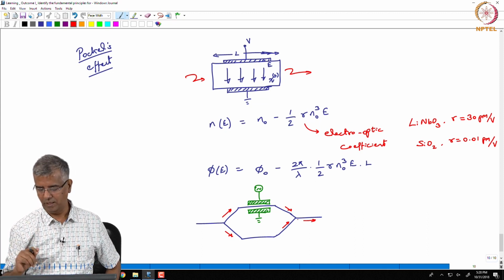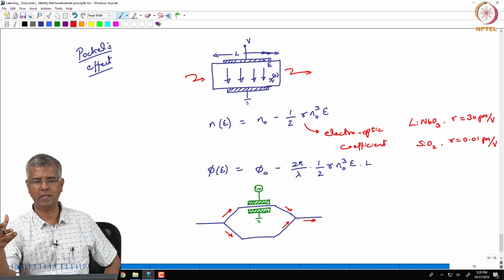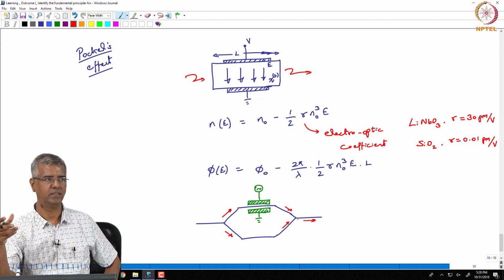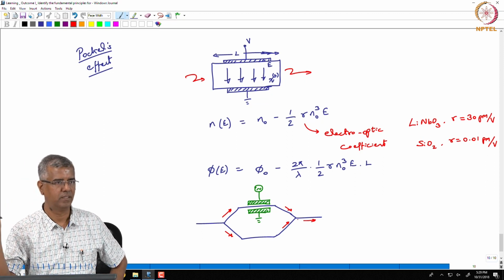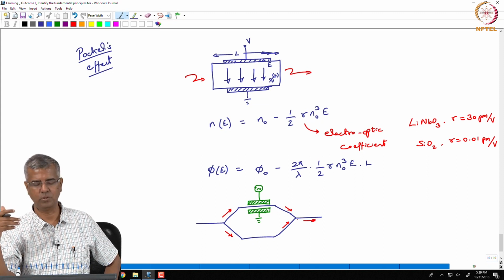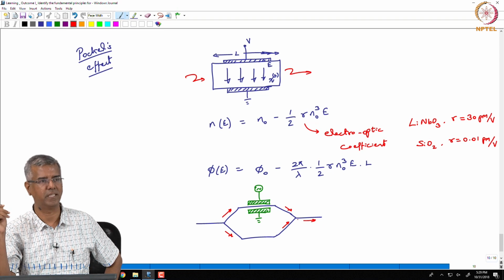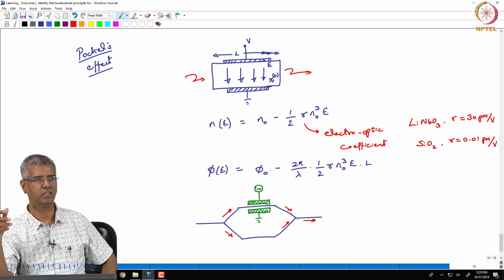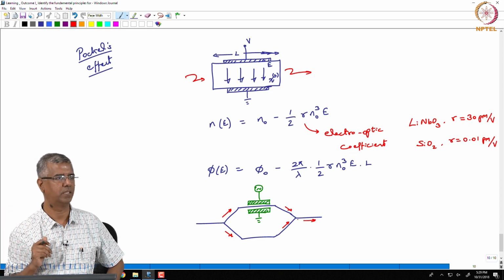So, if I want to communicate data, I have my data, I am speaking now, and let us say this is actually transmitted live somewhere. You are digitizing the voice, you are digitizing the video, you communicate that as data. That data is available as a voltage. Now, you want to send this over a long distance. So, you are going to try to put this onto an optical signal and send it through an optical fiber communication system, right. So, you need some device which can convert these voltage changes into changes in the intensity of light. That will be this sort of a device, okay.